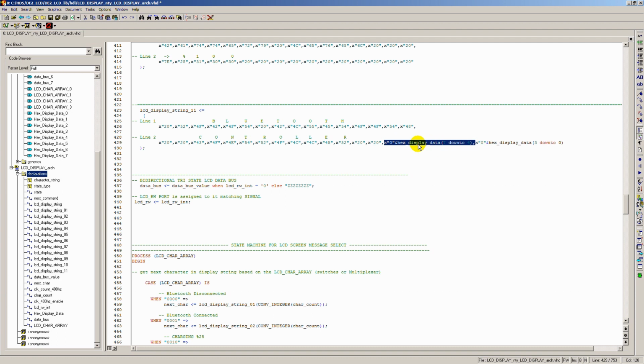essentially. If you replace this particular variable for a particular hexadecimal number, you're controlling that particular character on the string to be represented by a specific set of switches that we've mapped to this variable. So whenever you would change the condition of, say, 4 switches, it would determine which character would be displayed for this particular character within our sequence on our LCD display string.